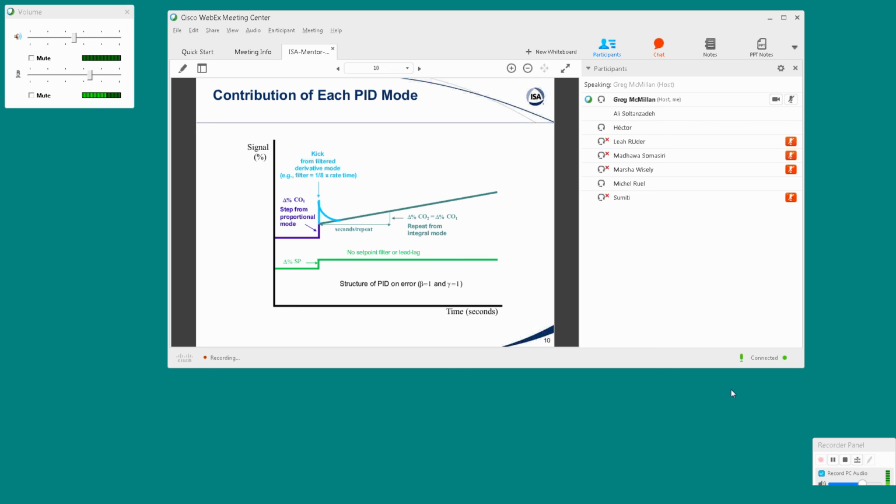Michelle, you want to comment on that? Because I know you've been working on this. Greg is saying that, yes, with the tools we have today, we can be in auto, and we will just add a jitter signal on the set point. So very small changes, very quick changes. And we will be able to capture the model very quickly if it's integrating or runaway. And the main point is you remain near set point. You don't move away from set point.